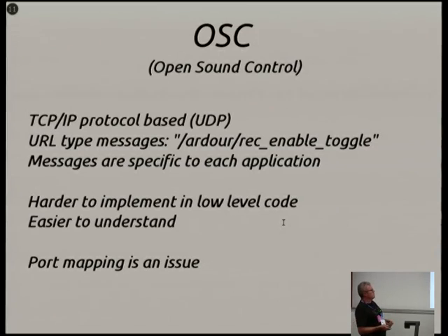An application can say, these are my standard set of interfaces, and it's not going to clash with anybody else's, hopefully. If you're writing at the microcontroller level, of course, this becomes a lot harder because you are doing a lot more work. You've pretty much got to store 20 bytes before you can even make a decision about what you're doing. You've got to have a whole TCP/IP stack sitting on your chip. So for that small microcontroller stuff, it's not as great from a programming point of view.